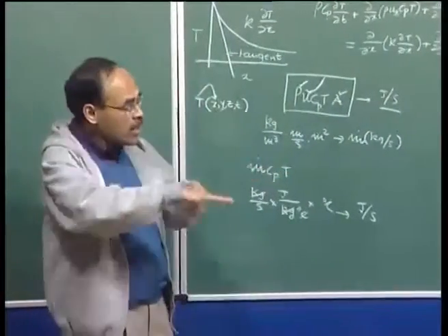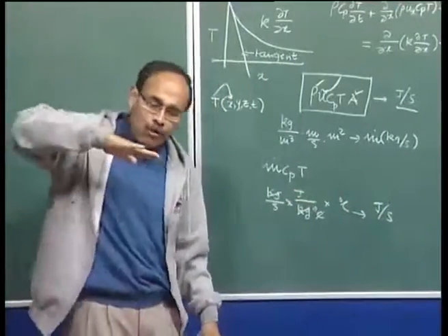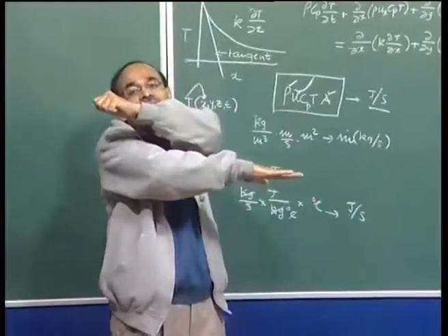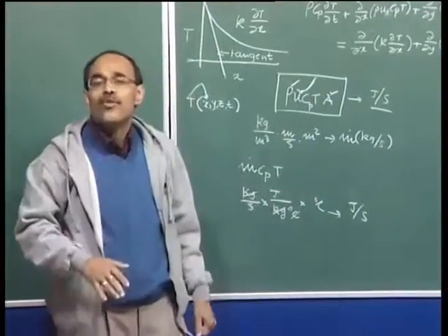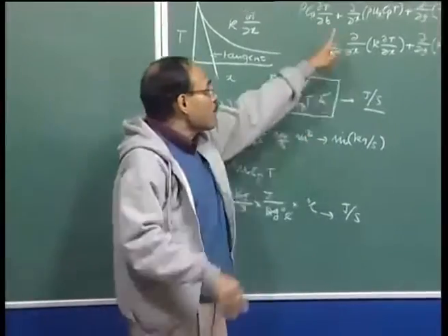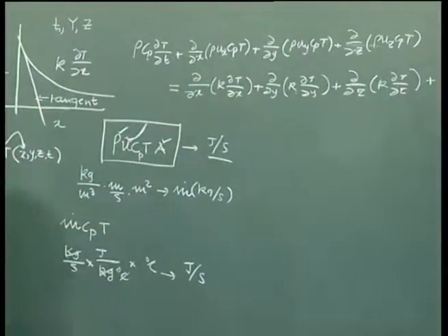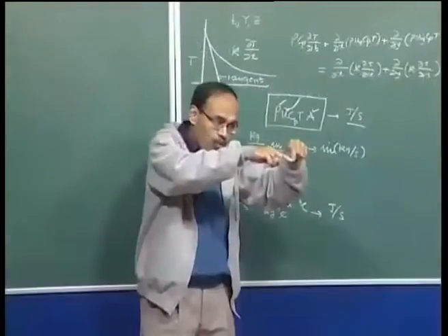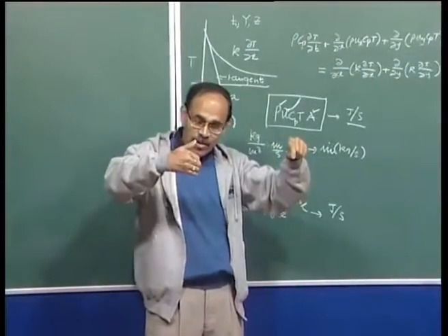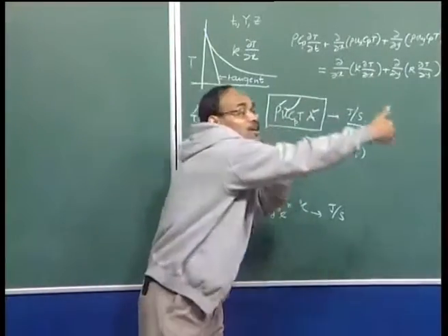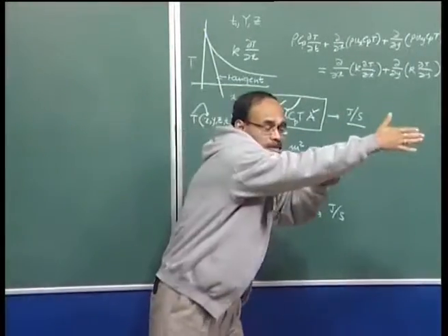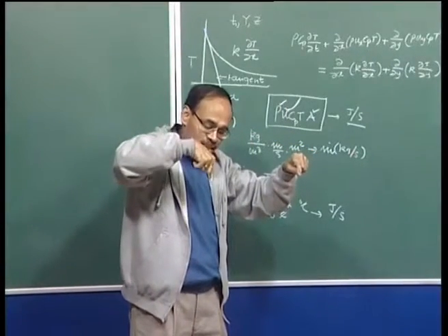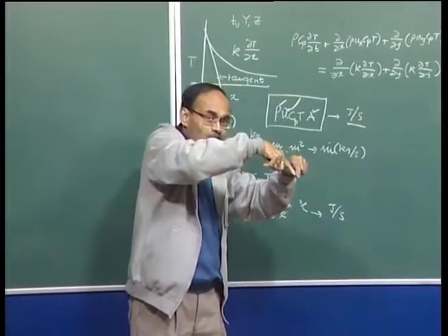But now imagine heat is flowing in this direction. So the fluid is flowing in this particular direction. So for heat to flow the large distance opposite to the direction of the flow is going to be very, very difficult. So this is the one way behavior of the term, this is the first order derivative. So the condition at a point will determine what is happening on this side of it. Okay, it is not dependent on this side. So if the fluid is flowing in this particular direction, the heat at this particular point will depend on what is here. How much heat is here, that will determine how much heat is flowing here and not what is there.